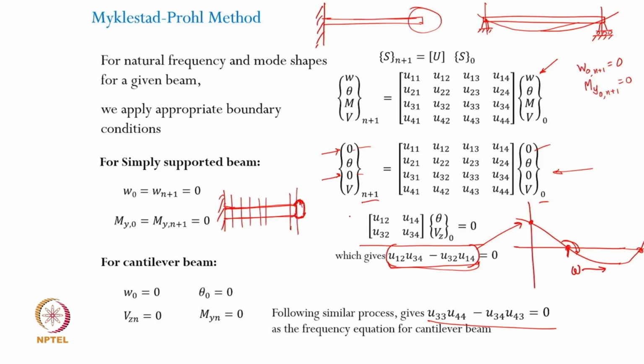So the transfer matrix corresponding to the end segment here will have in your point mass, the mass which is located here, mi into omega square. So this Mi will be not only the mass of this segment, but I can use this mass, the tip mass, to get added to it.